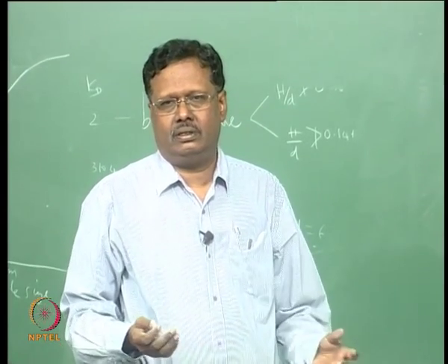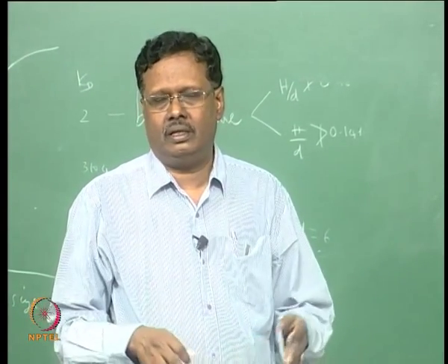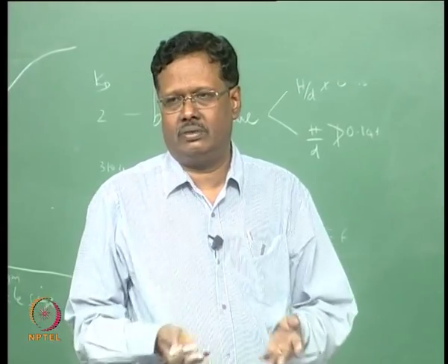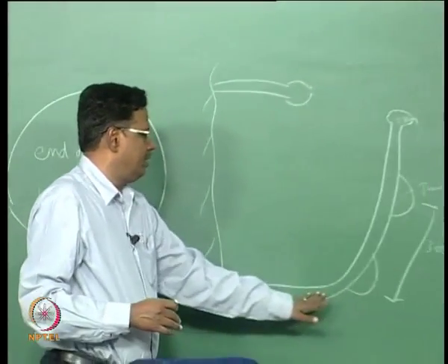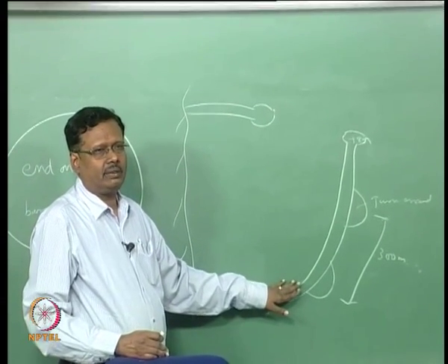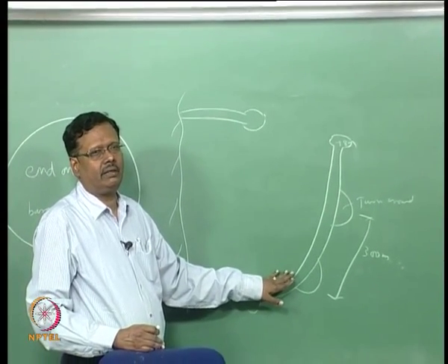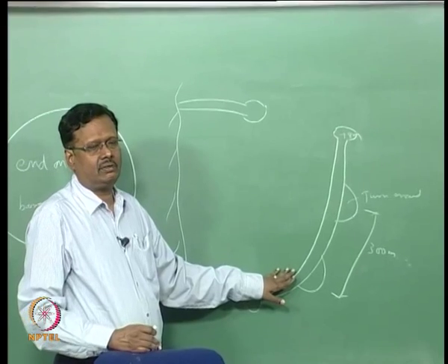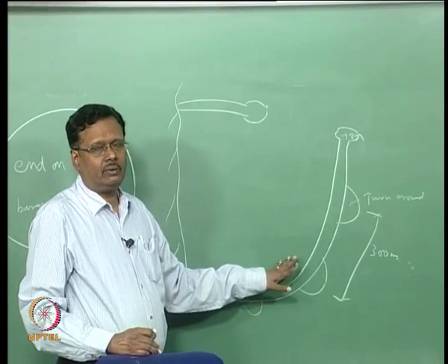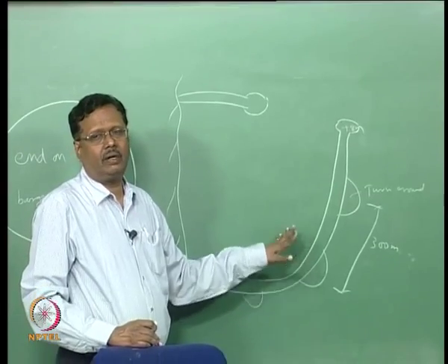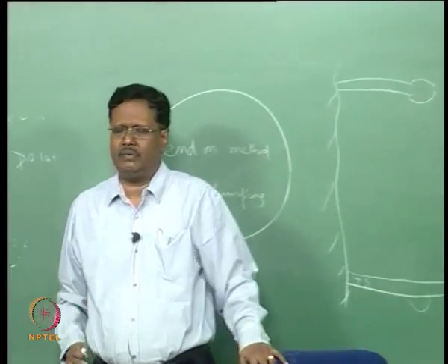Barge dumping means you transport all the material into a barge. It is a split barge which will open at the bottom. Suppose they have constructed up to this point, the barge will go and dump at the bottom. The core layer and the filter layer will be dumped by the barges as well as the tow mount, because it is very difficult to use a crane to dump it, but the barge method of dumping is preferable.